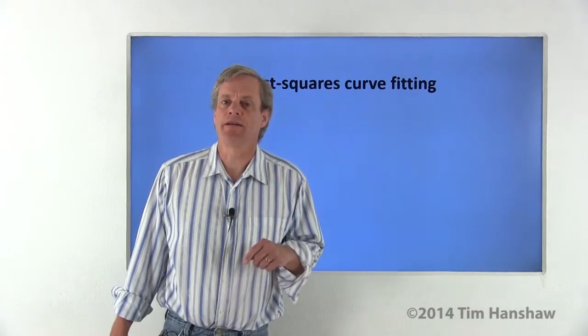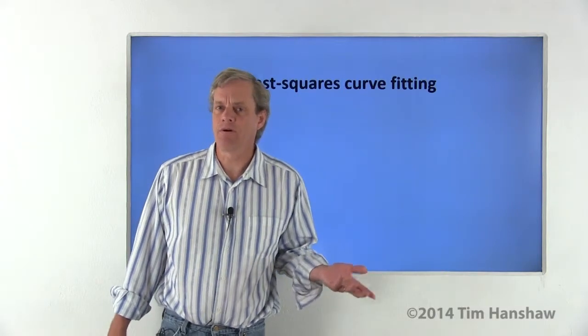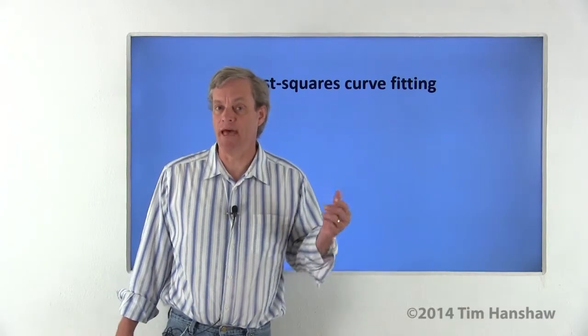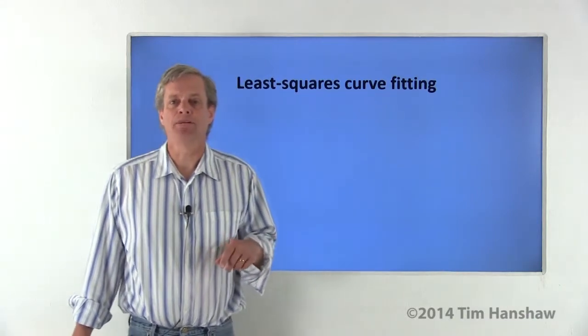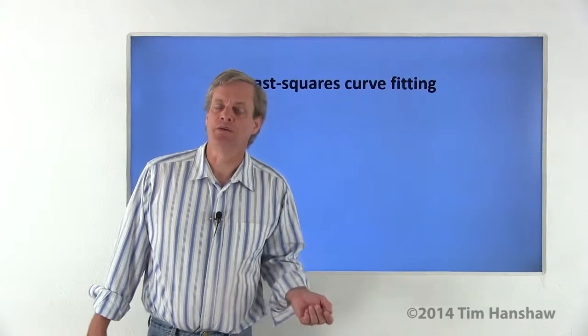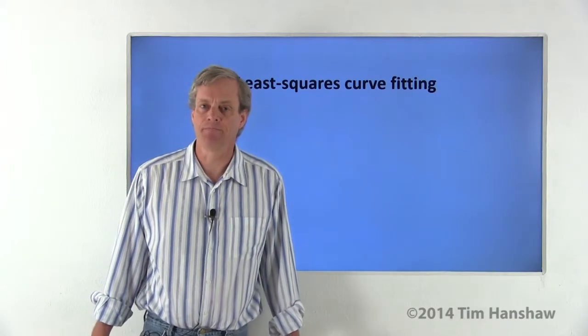One way to get this model is to create a line that you feel best describes the data. There are a variety of ways to define best. This tutorial will demonstrate how to use Matlab to implement one of the most common ways to do this, which is a least squares fit of polynomials to a set of data.